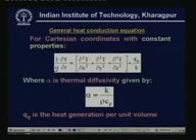Of course, there are a wide variety of ways by which you can solve this particular equation, and you can derive similar equations by applying Fourier's law and first law of thermodynamics to other coordinate systems, for example in polar coordinates, etc. And this is typically a partial differential equation, and if you want to solve this equation, you need to know certain initial and boundary conditions. So with the help of the initial and boundary conditions, you can solve this equation and get an expression for temperature in terms of x, y, z and tau.